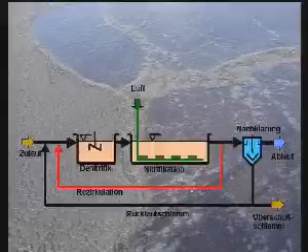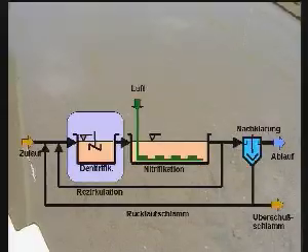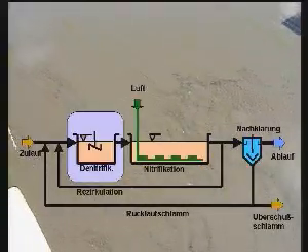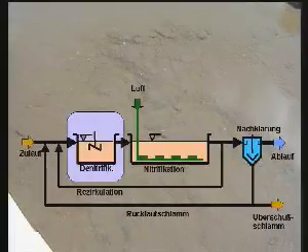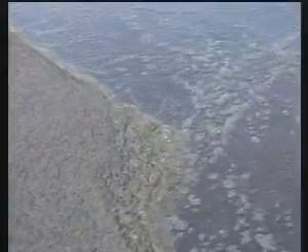The nitrate-rich wastewater is then channeled by internal recirculation to the denitrification zone. Here, under anoxic conditions, that is without dissolved oxygen, the nitrate is broken down into elementary nitrogen and oxygen. The biological breakdown reactions are triggered by the bacteria in the sludge flakes. The concentration of sludge or solids in the activated sludge tank is therefore of central importance for the treatment process. This concentration is externally influenced by the hydraulic load and internally by the sludge recirculation flow. It is therefore essential to monitor the total solids content in the activated sludge tank.